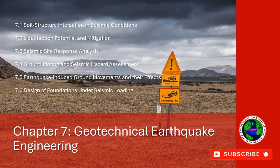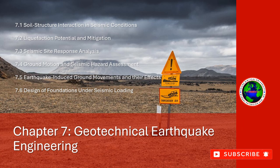7.4.2 Methods for ground motion prediction. The prediction of ground motion at a site involves using statistical models that estimate the expected amplitude, frequency content, and duration of seismic waves. These predictions rely on seismic source models, the distance from the fault, and the site conditions.